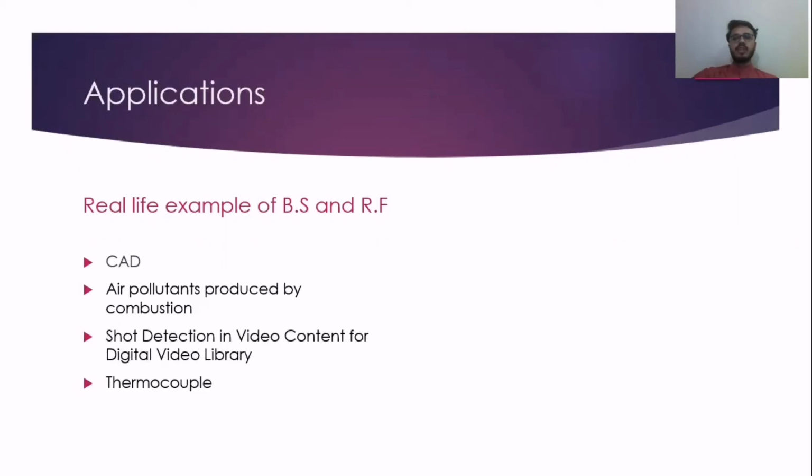The answer is when we have to draw a certain geometry on CAD which has some curve parameter, like drawing a 3D model of a car. So here to represent curve geometry, different types of curves are used like Bezier curves, B-spline, etc. And they all have certain control points to control or manage the behavior of the curve.